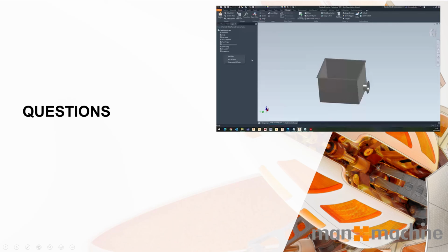Often, it depends on your modeling practices at the end of the day. If your model's been built well and you've used your origin planes in a manageable way, you'll probably have to break it apart and do a lot of reconstraining in the assembly. There'll be a lot of work in the assembly anyway, because you'll need to reference things and have clear parameters to drive to. If you've used the default parameters in your parts, it's going to be very difficult to remember what d0 to d400 is in parameter naming. So we would need unique parameter naming. It's just going to depend on what level that model is.